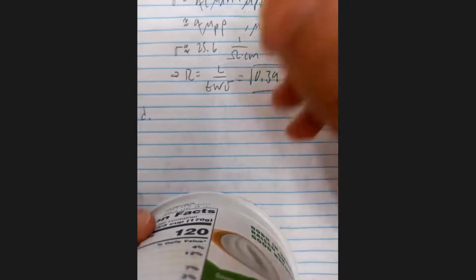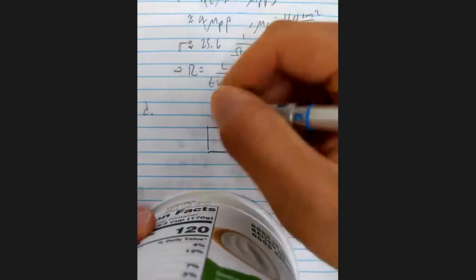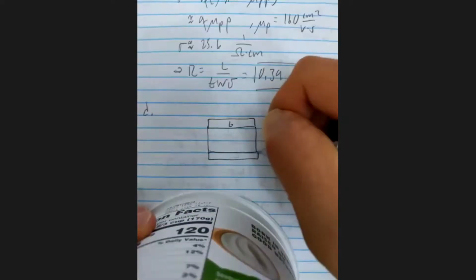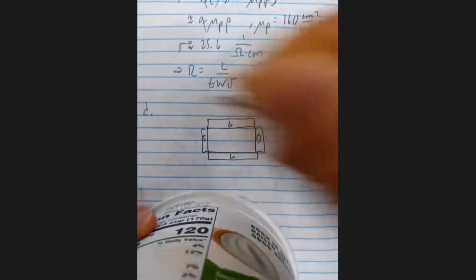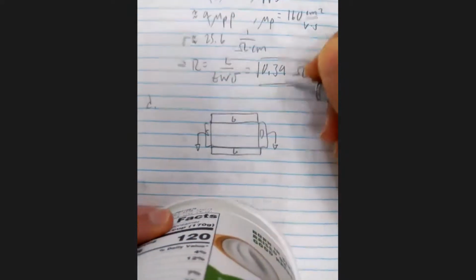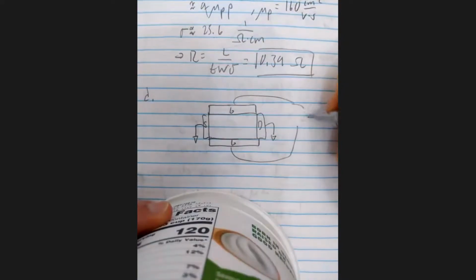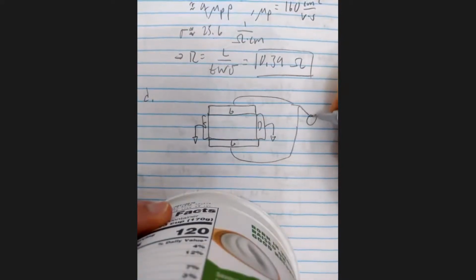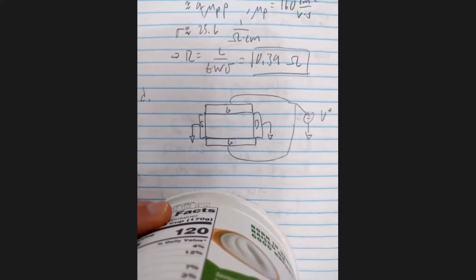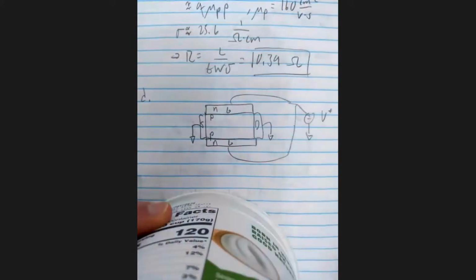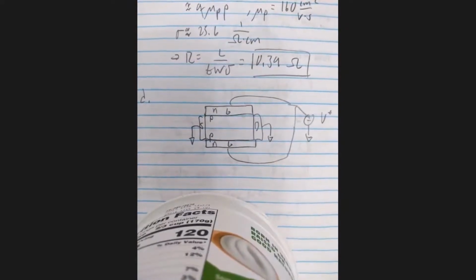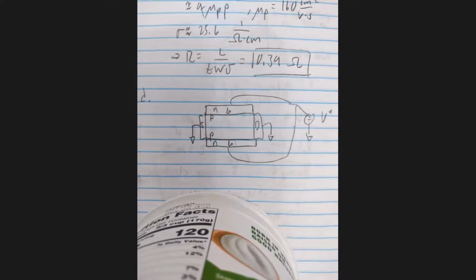So I'll draw this up. We have our body in the middle. We have one gate, we have another gate. And then I think this one is the source, and this one is the drain. We're going to ground these two, but we're going to apply some positive voltage over here, V plus. We want to see what's going to happen in this structure. More or less, this is testing if you understand how p-n junctions work, and how this is a p-n junction and what type of p-n junction this is.